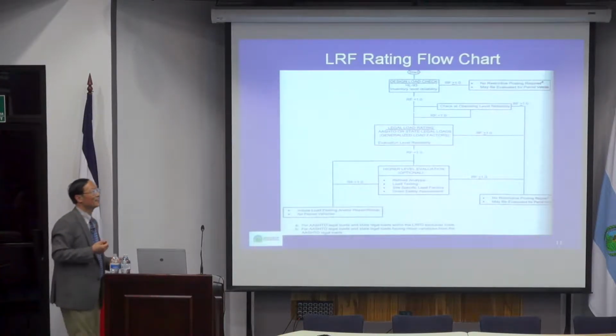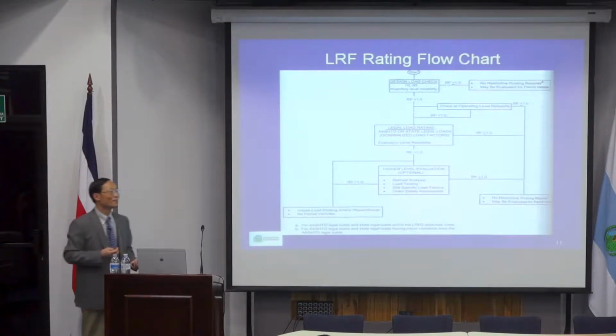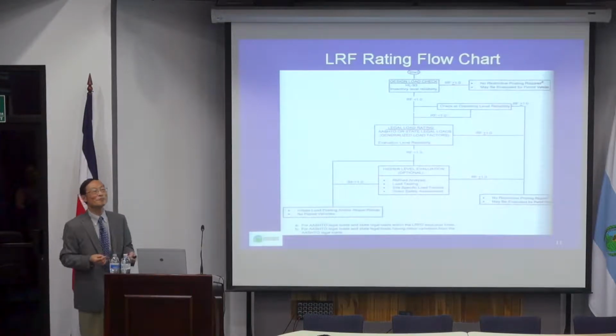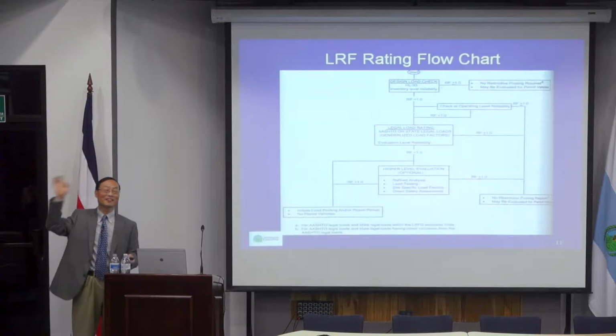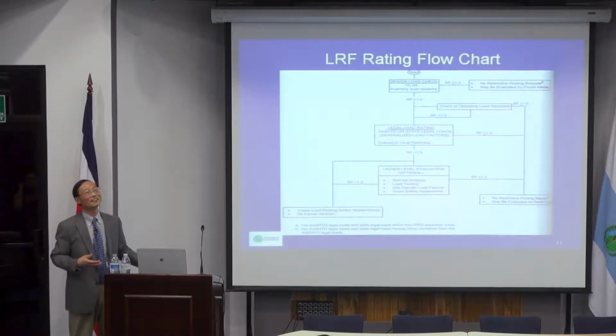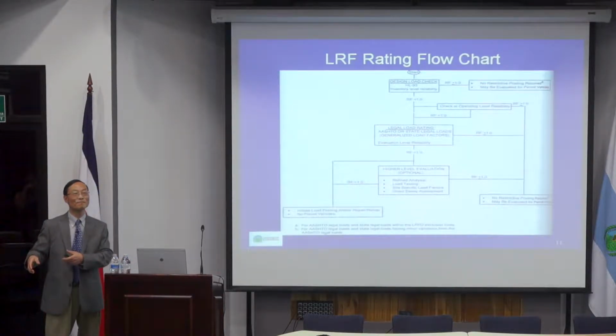But there are a lot of such structures, and people realize that for a lot of bridges, when you do the calculation, it does not work. But if you go to the bridge site, take a look, and the truck comes over and has no problem, then it means the truck is okay, the bridge is okay. So for these types of bridges, they actually allow you to have another avenue to address that. You can do a load test.